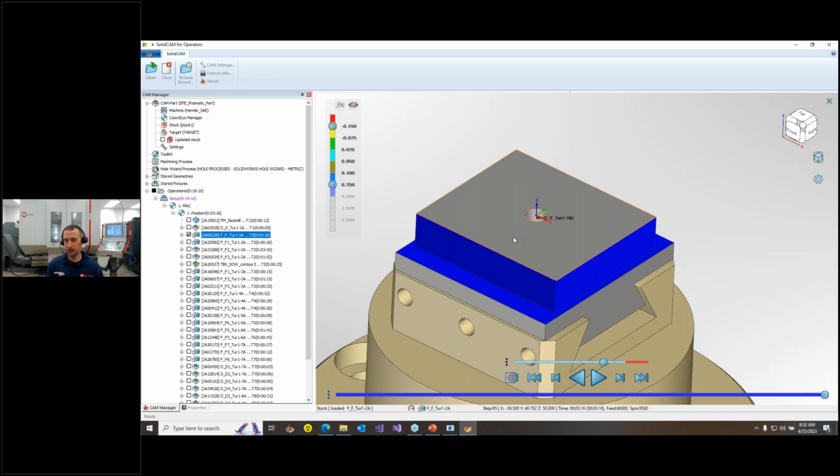I think everybody who knows from running machines knows air cutting is the worst, right? And when we're in CAM, it's really hard to see air cutting in CAM software, right? Because we're simulating fast. On the shop floor, this operation is taking, let's say, 3 minutes to cut around that outside. Well, simulated here, depending upon the speed, it's super fast.